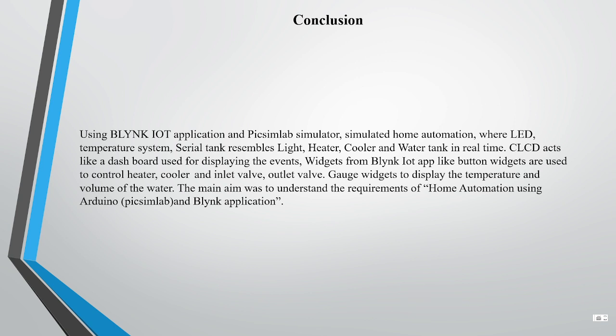Conclusion: using the Blynk IoT application and Proteus simulation, we simulated home automation where the LED, temperature system, and serial tank resemble light, heater, cooler and water tank in real time. The CLCD acts like a dashboard used for displaying events. Widgets from the Blynk IoT app, like button widgets, are used to control the heater, cooler, inlet valve and outlet valve, and gauge widgets are used to display the temperature and volume of the water.